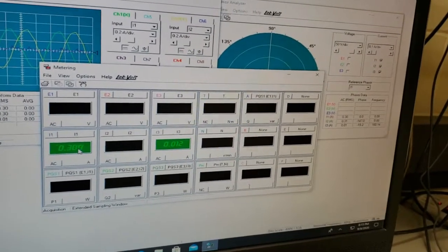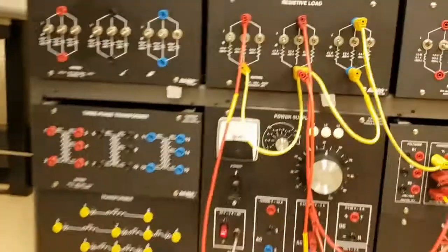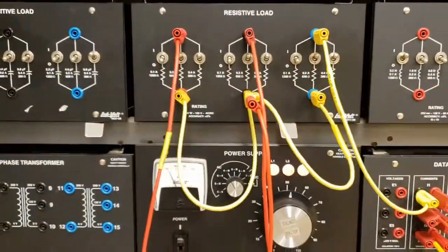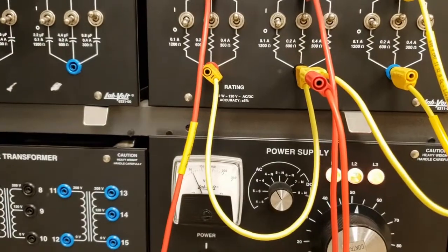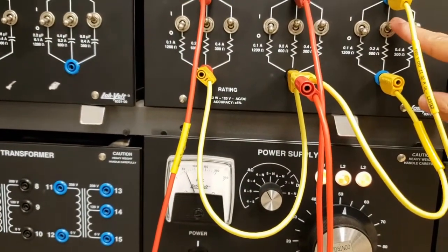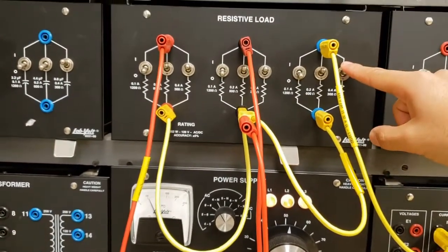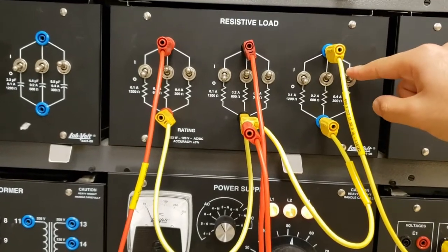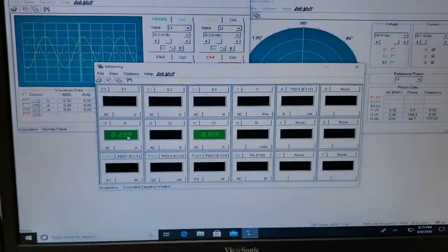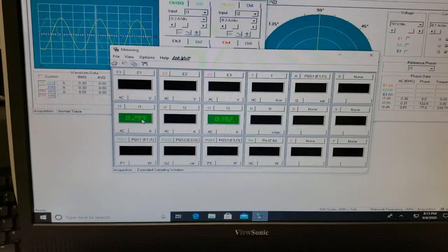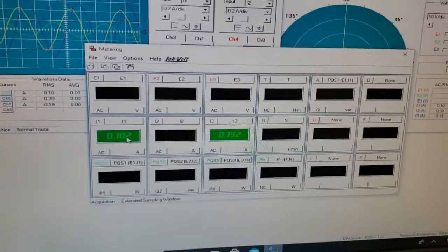Okay, and now to show you what happens when the load becomes unbalanced. So I have 200 ohm loads here with 60 volts, which is why you can see 300 milliamps. That makes sense. I'm just going to change any one of these loads. Let me change this to be a 600 ohm load, so it takes a lot less current. Well, guess what? That current has to go elsewhere. So if I do that, I made the switch. You can see now, look at the difference.